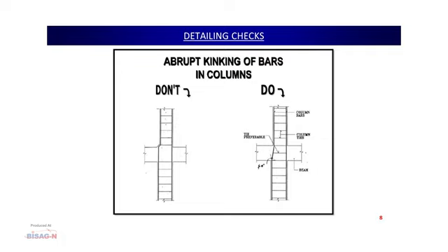So, what the bar binders generally do is they take the column bar up from the bottom, and when it reaches the top column bottom, they give just a kink, and then continue the bar inside. This practice is not recommended to be followed on the ground, because it defeats the structural integrity purpose of providing the reinforcement.